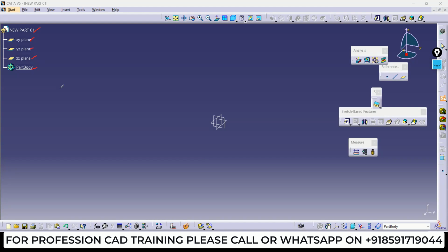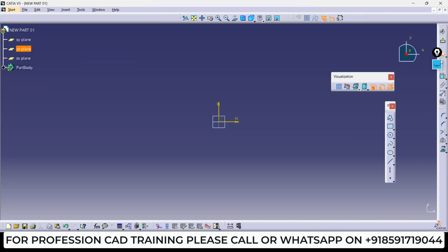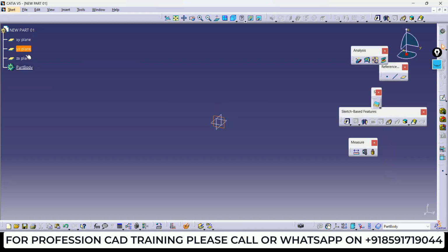What we did, we unchecked the hybrid design, right? No problem. Now, as per the steps, we need to select any plane. You can directly select your plane from here also, no problem. For example, I am selecting this plane. And then here you need to find the sketcher, this sketcher.